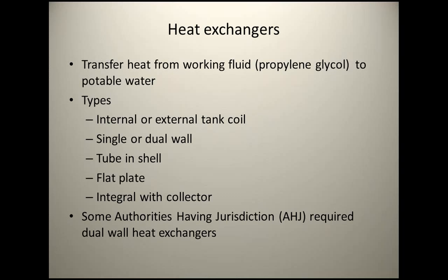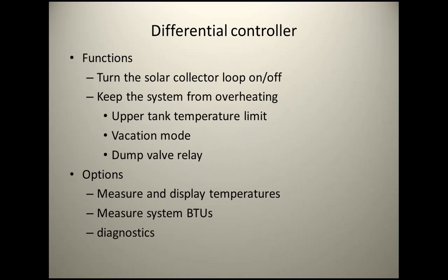Okay, so to avoid that, dual wall. You have two separate walls, and so if you get a leak in one, it doesn't go into the other. Okay, differential controller, we talked about that. There's an upper tank temperature limit. You can take various actions depending on what happens to that upper tank temperature limit.